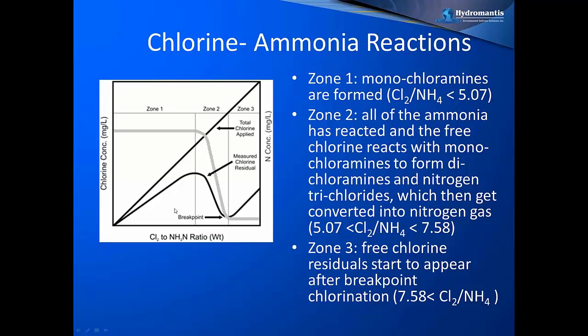And as the chloramine is a disinfectant also, it can provide some disinfection efficiency, while reducing the potential of disinfection byproduct formation. So this diagram is really important, and this is one of the key things that was required to be done in the model. In the model, depending on the ratio of the chlorine and the ammonia, we would like to generate this kind of curves.